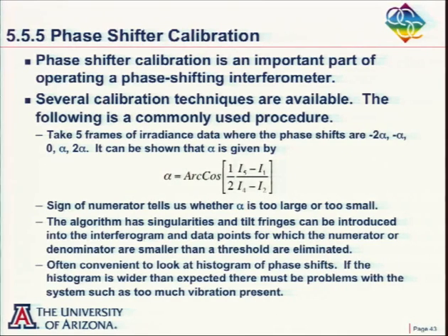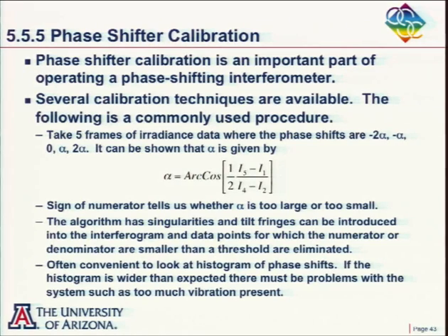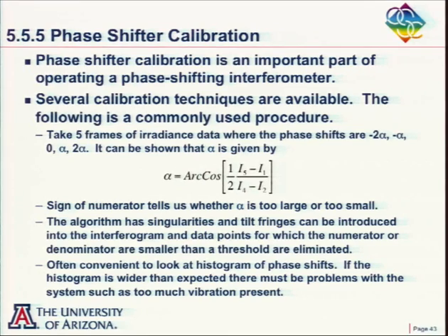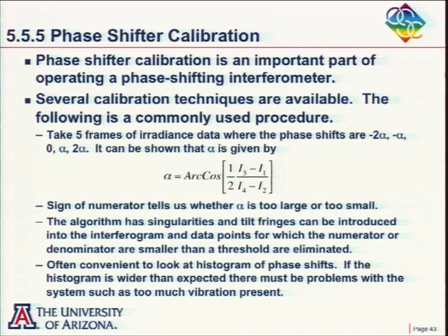So all of these systems have some type of a phase shifter or frequency shifter. And we said we want to generally use 90 degrees phase steps, but it doesn't have to be 90 degrees, but the algebra generally becomes easier if it is. And so we'd like to some way determine just what the phase step is and adjust a phase shifter to make the phase shift whatever it is we want. As I say, normally 90 degrees.